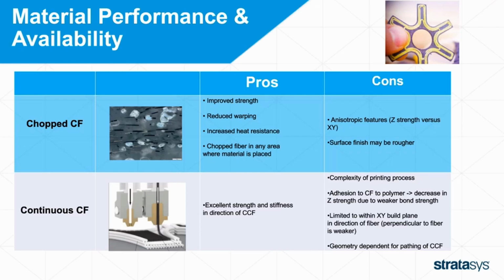So in the example up in the upper right-hand corner, we start to be limited by how thick those areas are, so it's not able to fill that carbon fiber all the way to the end for that most inner path. And then another thing with the continuous carbon fiber is that it's not able to cross over itself. So you can put it, but you kind of have to have a mentality of where does it go.